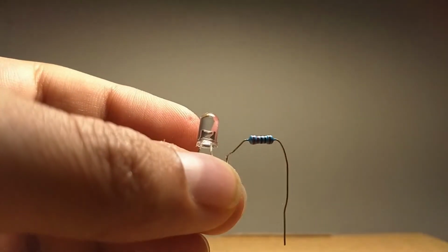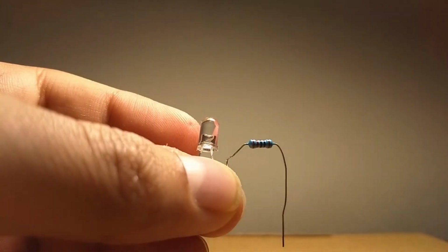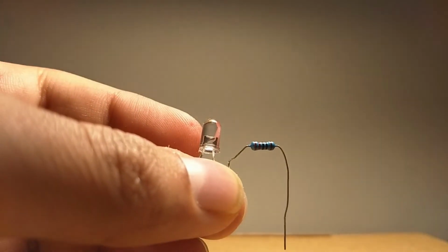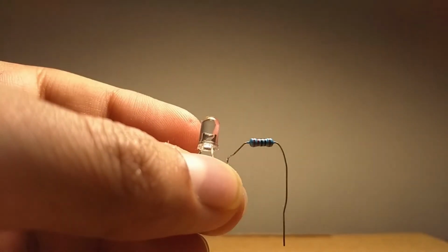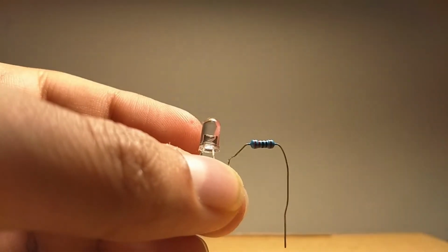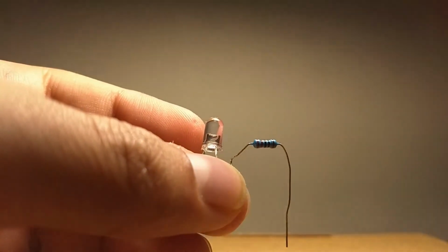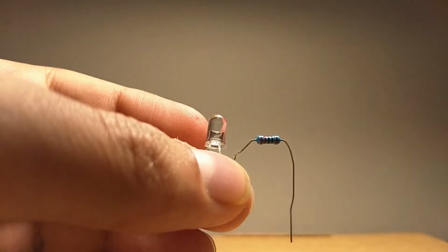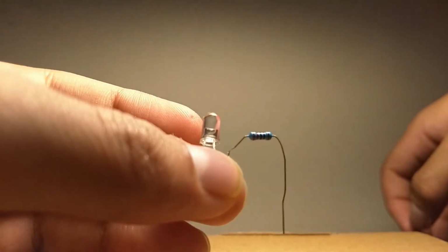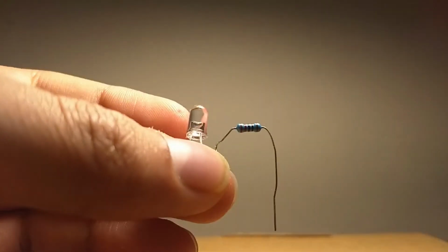The first two reds represent a value of 2 according to the table. Black is 0. The second to last band, which is black, has only one multiplier. So 220 multiplied by 1 is 220. The brown at the end is 1% tolerance, which means it could be 1% higher or 1% lower than 220.